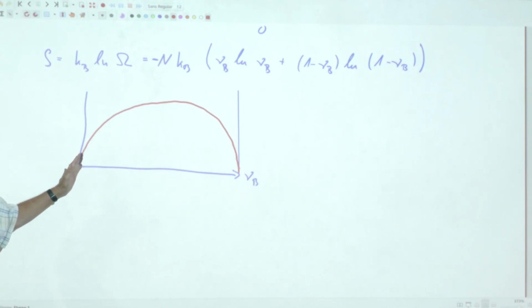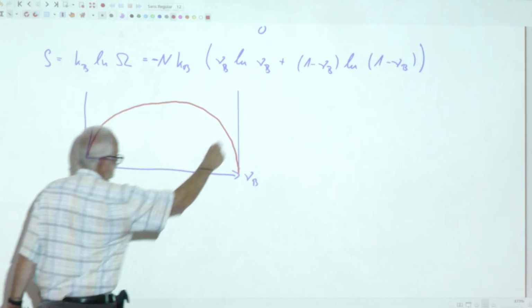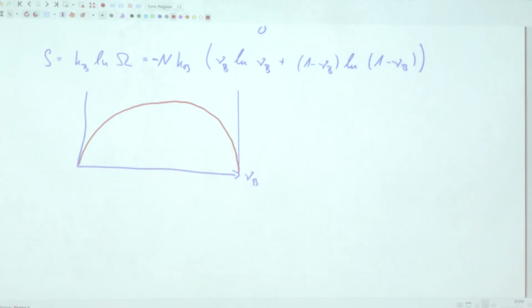So by adding very small amounts of these solute elements, you gain a lot of entropy, which at finite temperature lowers the free energy or free enthalpy. And this you have to fight in these purification routines. While the energy, in a similar approximation, the regular solution model, has a normal slope here. It's more like a parabola with non-vertical slope here. But that's only a side remark.